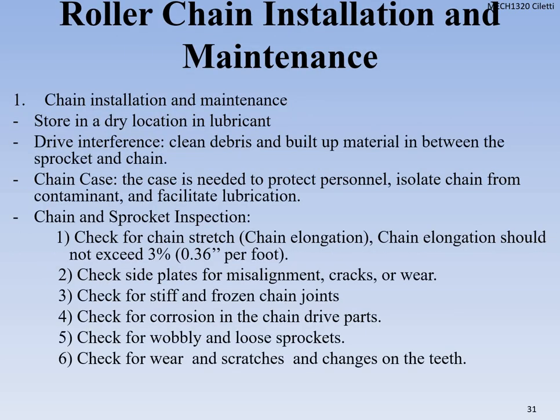Okay, I'm not going to talk too much about maintenance because you can read through all this, but when you get to your place of work, they're going to tell you what they want you to do and how to maintain a chain. Okay, most likely if you're using a chain, it's in use. All right, so as long as you're keeping the correct distances, and you're using the proper lubrication, you're monitoring it occasionally for misalignments, cracks, wear and tear, and that sort of thing, you're doing the right thing. Okay, so always look for those things.